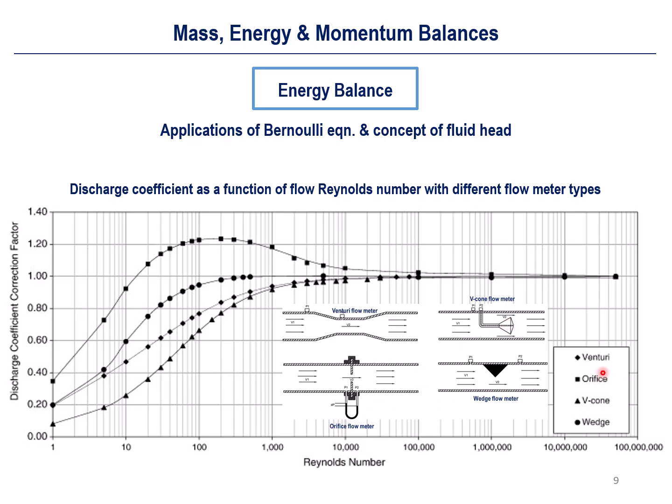So it is recommended for the engineers and the students to carefully select your flow meter, and once you get the information about your specific type of flow meter, you need to track down the reference data set, and with this data set, you can use interpolation or extrapolation, even if your Reynolds number is not shown in this plot. But I believe that most of the data points in your practice will be included in this reference plot.